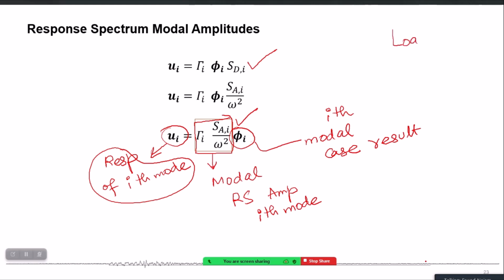We know that by default load combinations are meant for the purpose of structural design, but what they effectively do is they take the results of a load case and then multiply it with the factor which you provide, which is the load factor. For example, 1.2 times the dead load.